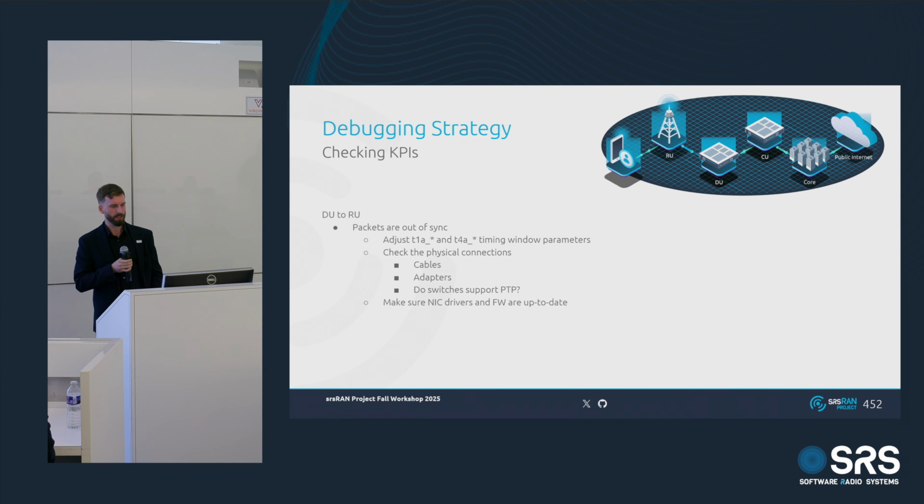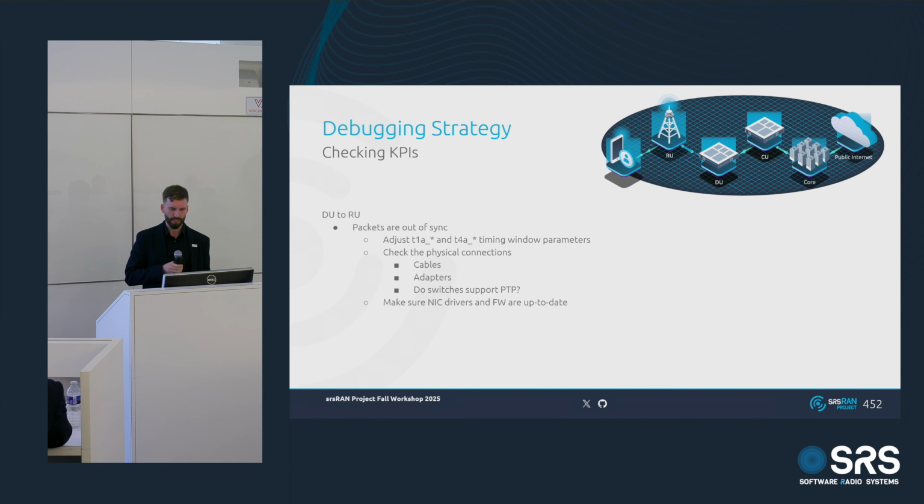And something else, some RUs have very specific timing windows. This is also something to consider here. Review the documentation of the RU and eventually adjust those parameters. Usually you don't have to. All of the RUs that we've integrated with have default parameters in our config files, so you find everything there. If you're integrating a new RU, make sure that this matches.